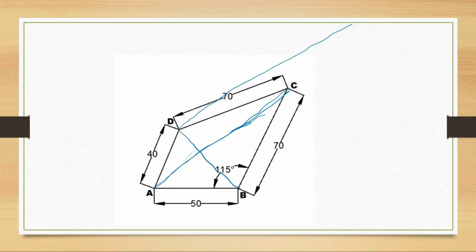Then the second thing you're going to do is draw a line, placing your drafter with BC, or you can even use a scale for that, and extend it till it intersects this line. This point will be O somewhere in the space.